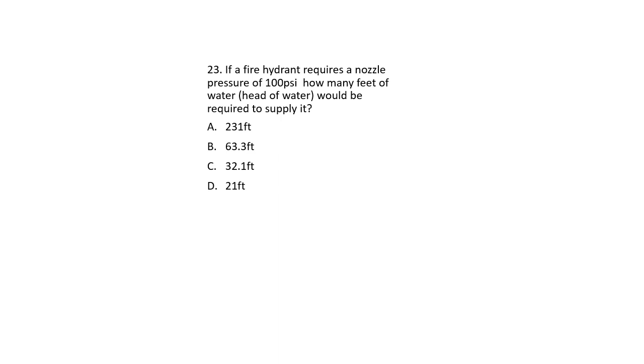If a fire hydrant requires a nozzle pressure of 100 psi, how many feet of water, head of water, would be required to supply it? 231 feet, 63.3 feet, 32.1 feet, or 21 feet? And the answer is going to be A, 231 feet. Again, most, as far as I know, places, a formula sheet will be given. So the head height of water, in feet, equals pressure, in psi, divided by 0.433 psi per foot.